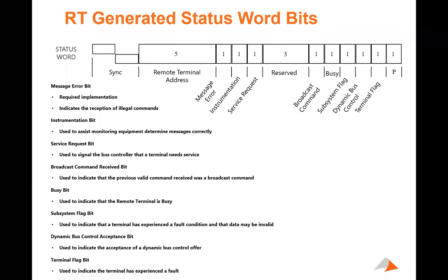It had to be predefined within the structure of the data bus what the bus controller would do if that particular terminal came back with a service request bit set, and then it would ask it questions, and that can also be done through mode code questioning. And it can be a rather neat way of implementing ad hoc questions into the bus controller.